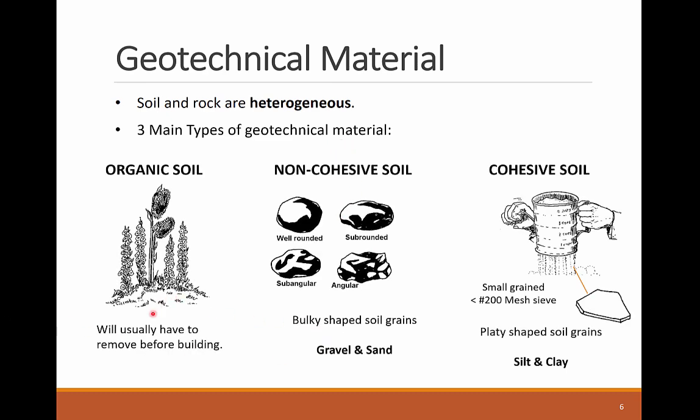First, organic soil is partly made of vegetation, which is the topsoil layer that exists naturally in a typical site. The soil has a spongy, unstable structure and cannot be used as a structural geotechnical material. As such, before the work is done in a project, the topsoil in a construction site is removed to reach a suitable soil that can be used in backfilling or retaining structures.